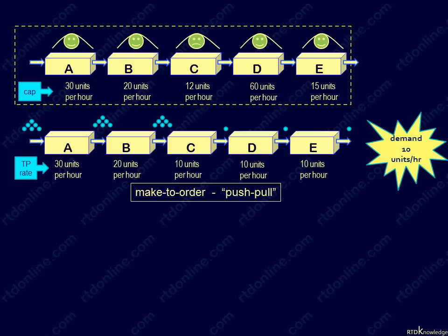There are no finished goods inventory as goods are immediately delivered or sold just in time. This can be considered a hybrid just-in-time system with just-in-time delivery but without just-in-time production, since work-in-process inventories are created in the upstream processes. Here the upstream stations are pushing with their capacities, but the downstream stations are being pulled by the market. Now, why would anyone want to do this complex production?